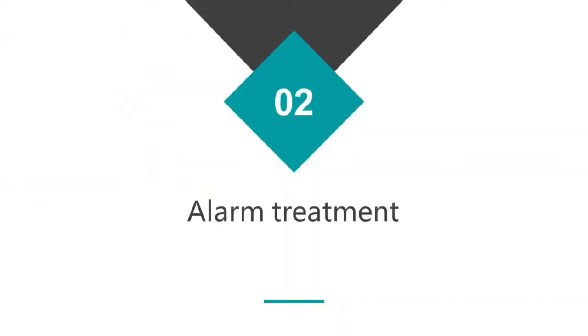For the alarm treatment, alarms are those protections which could be reset automatically when the external conditions get normal. All the alarms start with the character A, such as A.LFR, which Mr. Jason just introduced. It is a low-frequency protection alarm.